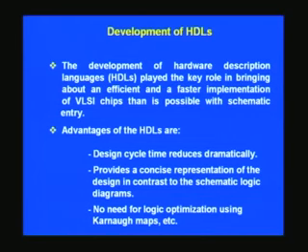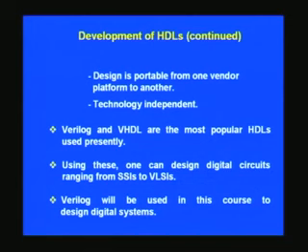And in contrast to this, in schematic you have to really put gate by gate, and it will take quite an effort to achieve the same end result. And there is no need for K-map and Quine-McCluskey way of reduction, because the synthesis tool is supposed to take up this role. And HDL designs are portable from one vendor platform to another.